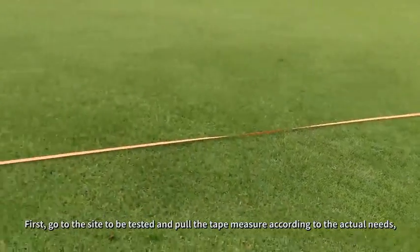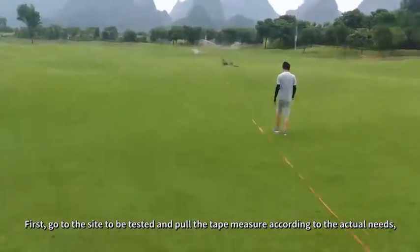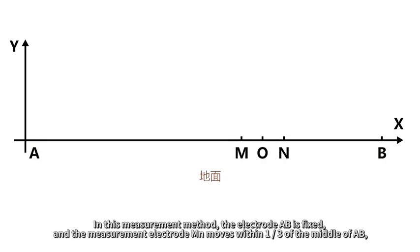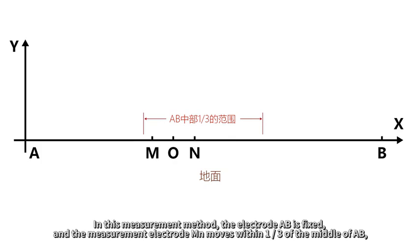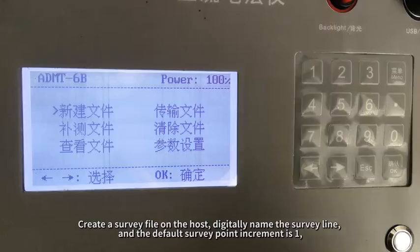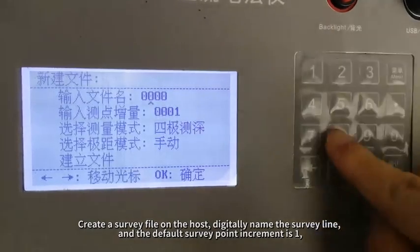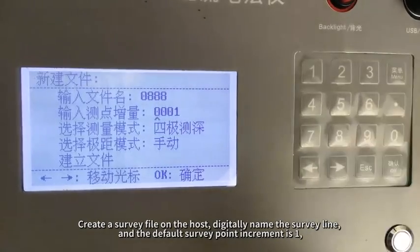First, go to the site to be tested and pull the tape measure according to the actual needs. In this measurement method, the electrode AB is fixed, and the measurement electrode MN moves within 1/3 of the middle of AB. And the MN pole can be measured on a parallel measuring line within the range of AB/6 away from the AB line.